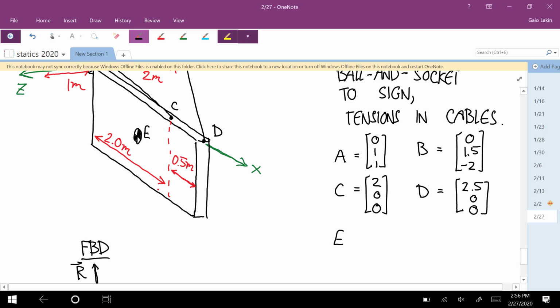And then the center of mass at E, in the positive x direction, the whole thing is 2.5 meters. We're going to the midpoint, so 1.25. For y, it doesn't matter because the weight force is vertical. And then for z, it's 0. So this 0 here, it's not really at 0 in y, but that's like we just moved that force along its line of action.